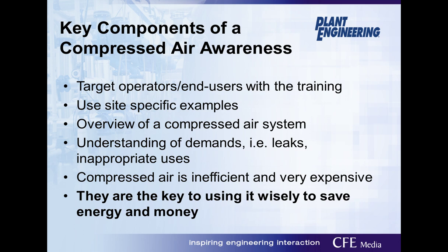So the key components you want to have in an awareness program: you want to target the operators and end use for the training. That's going to also include maintenance folks as well. You want to use site-specific examples. It's always better if they can see something that they see every day. You want to give them an overview of the compressed air system, an understanding of what the actual demands are, what leaks are, inappropriate uses. You want them to understand that it's inefficient and very expensive. And the real thing that you want to get across is they are the key to using it wisely to save energy and money.